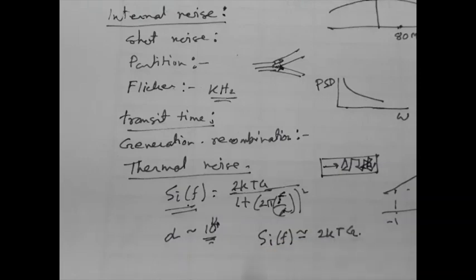So the power spectral density of the noise is considered to be constant, and the noise power in any circuit is determined by the bandwidth of the circuit. Thermal noise may be considered to contain all frequency components in equal amount. For this reason, thermal noise is often referred to as white noise. White means an equal amount of every color present in the light, and that light is called white light. With this analogy, we call it white noise. This thermal noise is also called Johnson noise.